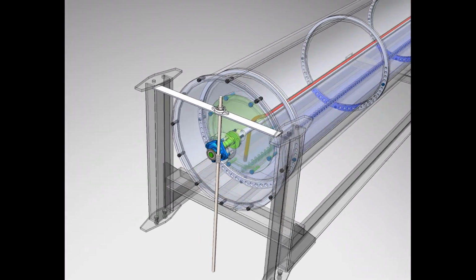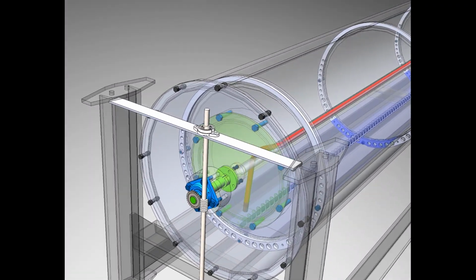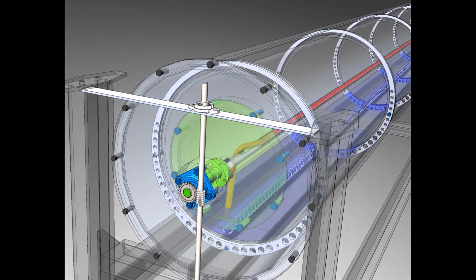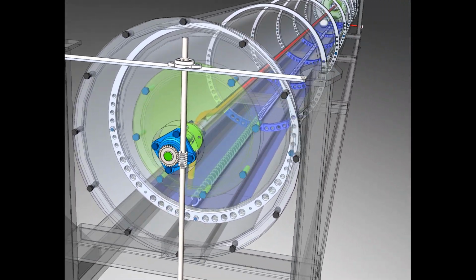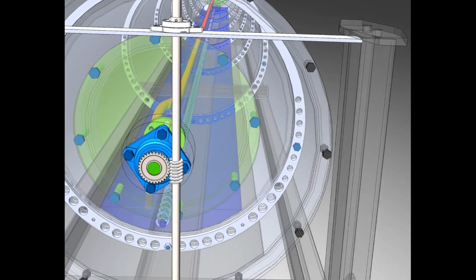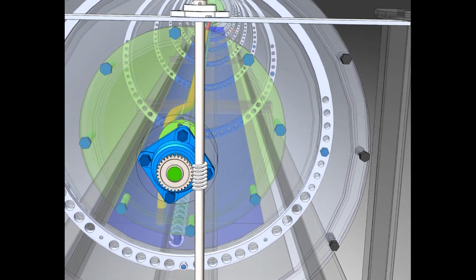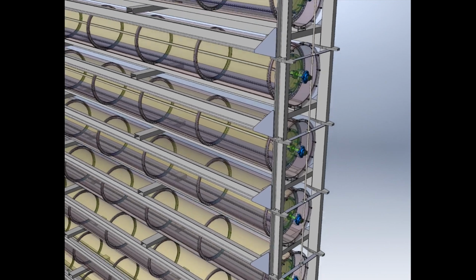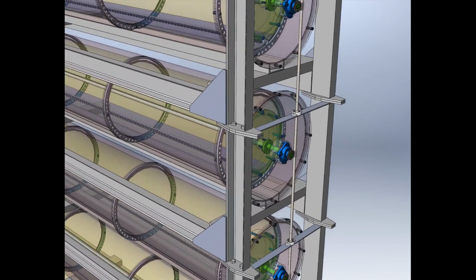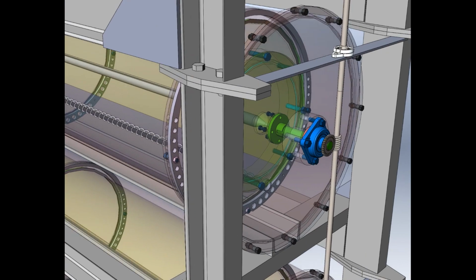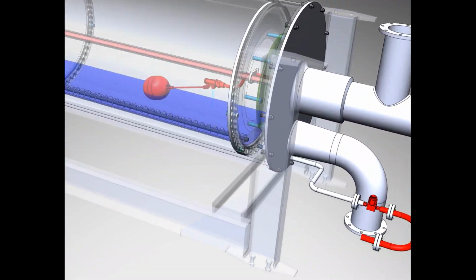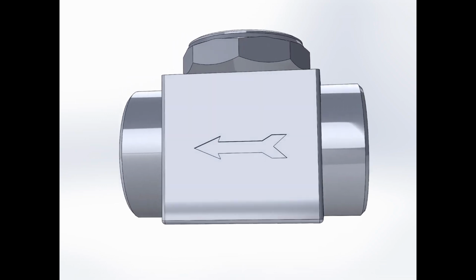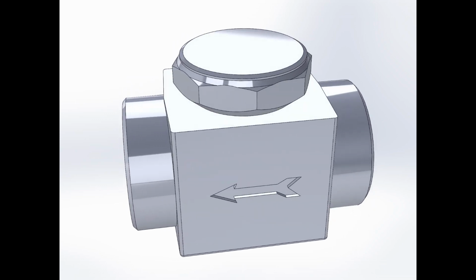In the FED design under consideration, drum rotation is ensured by a worm drive. The drum shaft is driven into rotation by a worm wheel, which is coupled with a worm screw. With a vertical arrangement of FED modules, the worm wheels of all drums are driven by a worm screw located on the same shaft, which can rotate from one drive, for example, a gear motor. Clean water from the FED, condensed on the outer surface of the rotating drum, is drained automatically through a thermodynamic condensate drain.